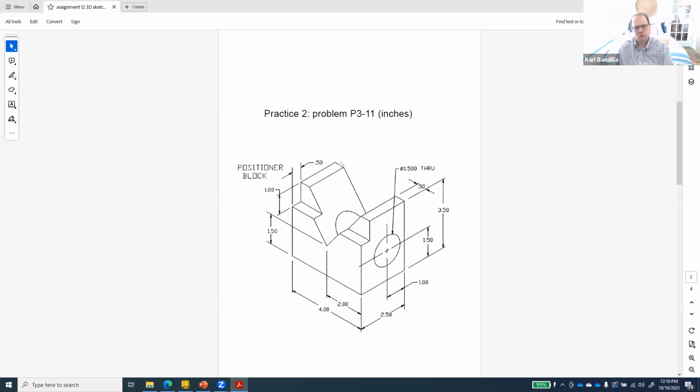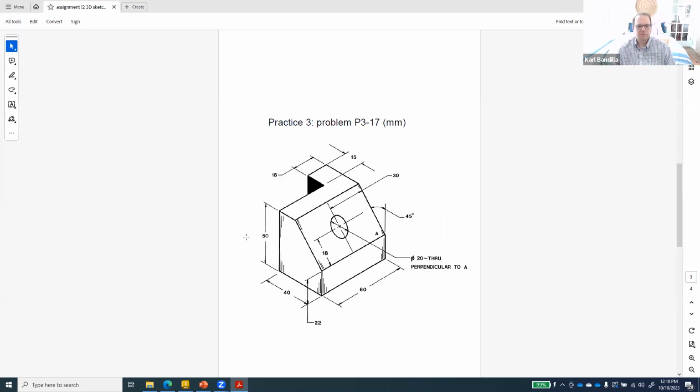I think I would just do a big solid block, and then I would cut this wedge out, by doing a drawing on basically this front surface. Then I do a drawing on this surface with this shape, do the cut through, and then the hole, and then you're done. So that would be that one. This one right here. There's nothing else going on in the back. There's nothing special happening there, so you don't have to worry.